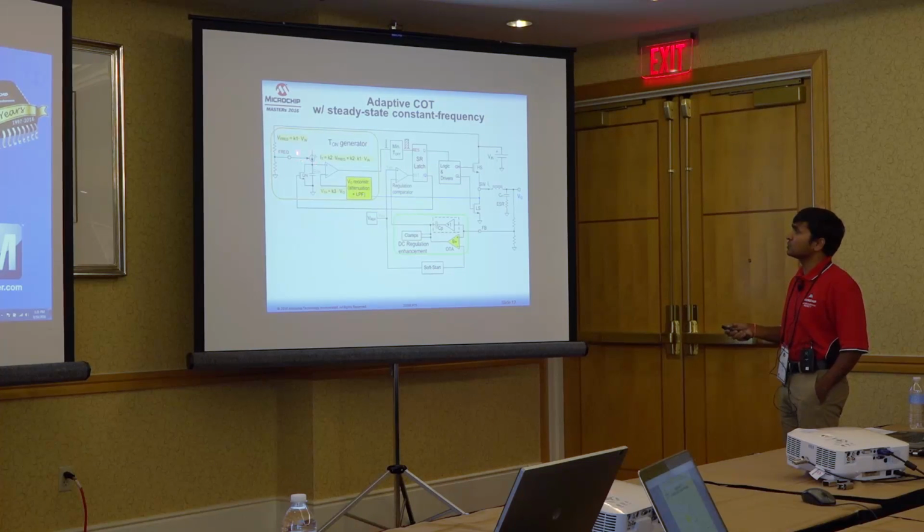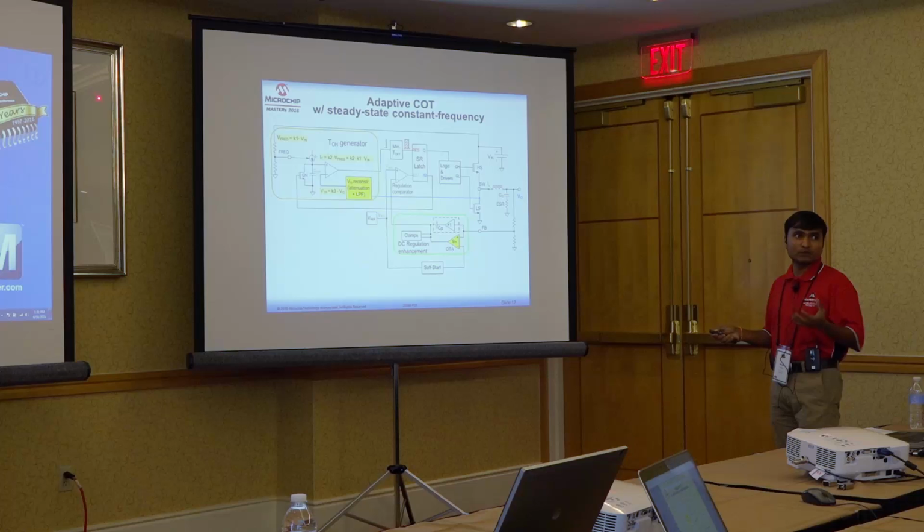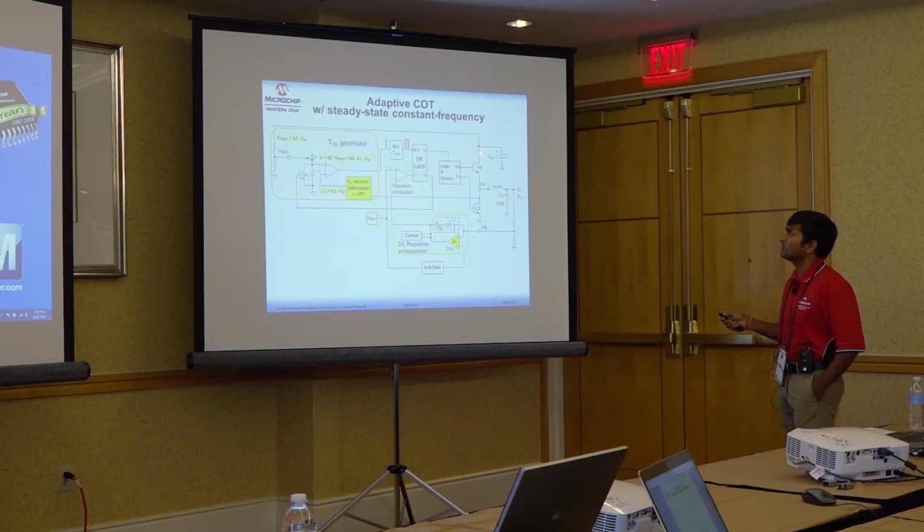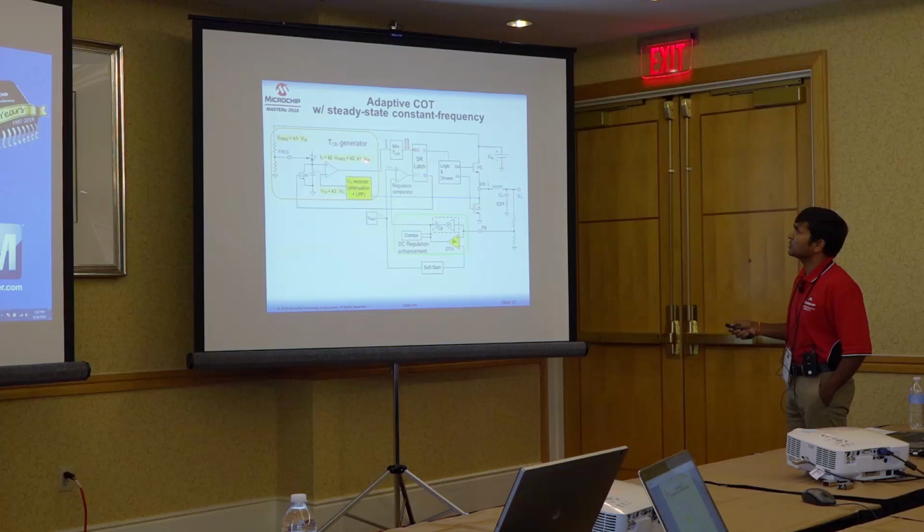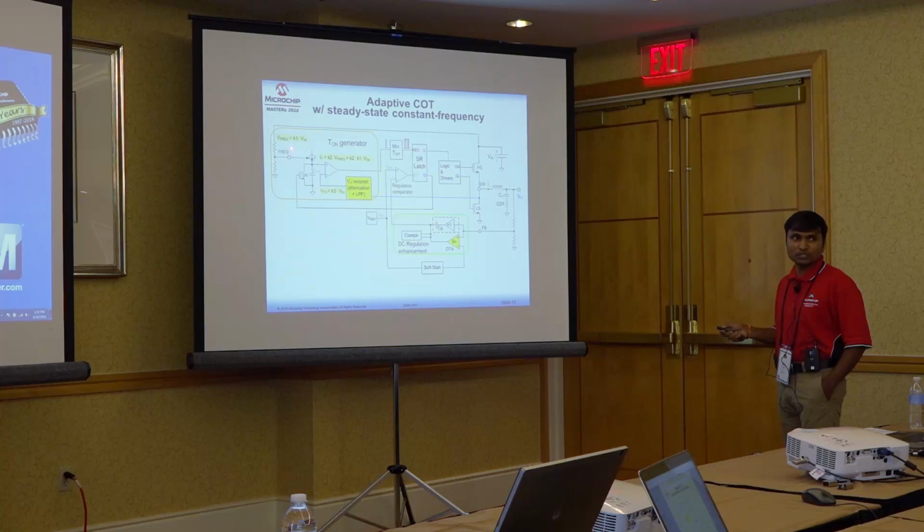In some of our controllers you see the frequency pin. So, now the constant current is proportional to the frequency pin input voltage, which in turn is proportional to the input voltage. That means the current is proportional to K2, K1 and V in. K2 and K1 are constants coming from the resistive dividers.